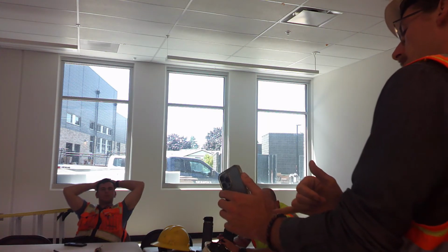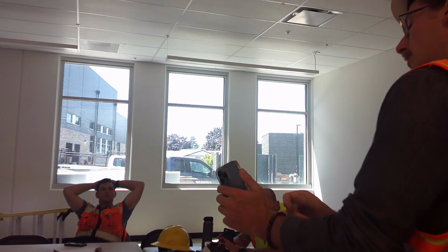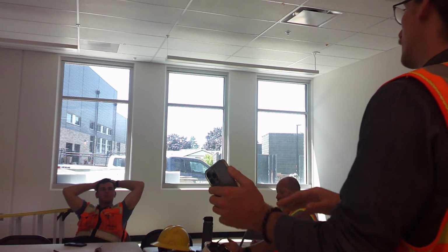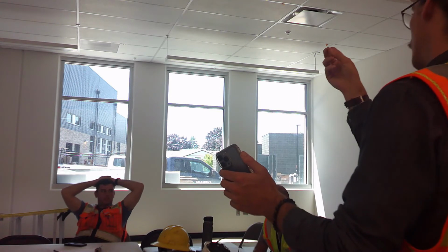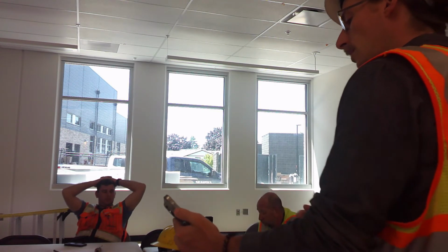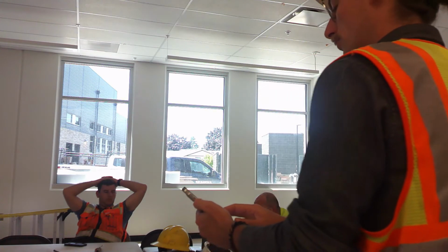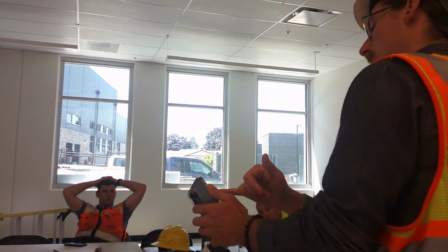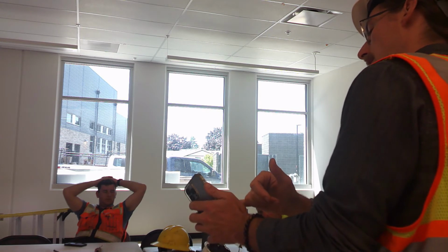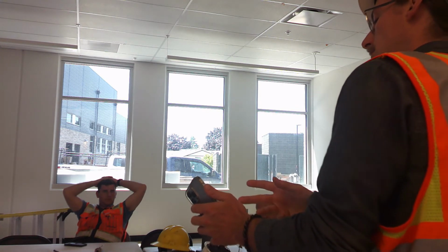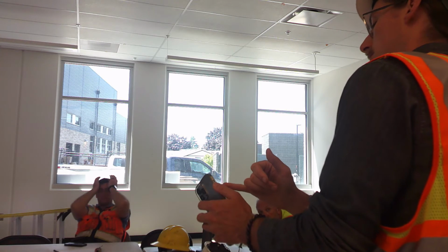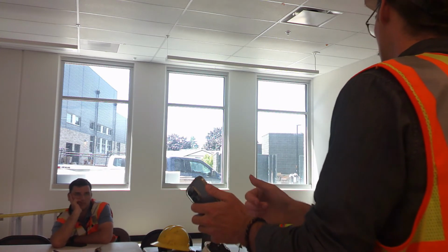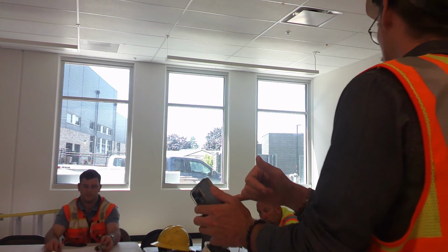In this page, this is your photocell calibration, and this determines how much the lights dim based on how much light the photocell is picking up. So in this room, for example, we've got our design and our task at 50. The easy way to think about this is the design and task create a ratio that then gets multiplied by the sensor value.